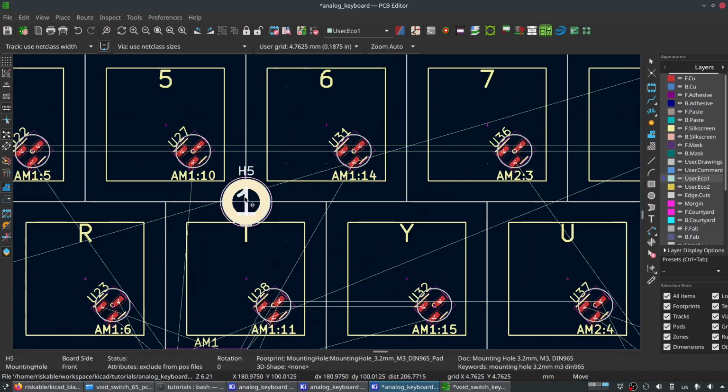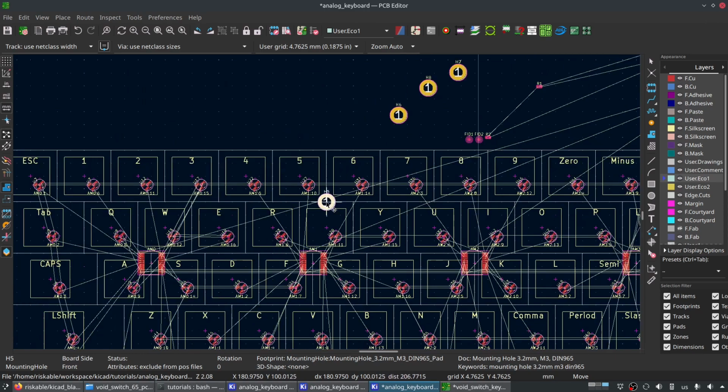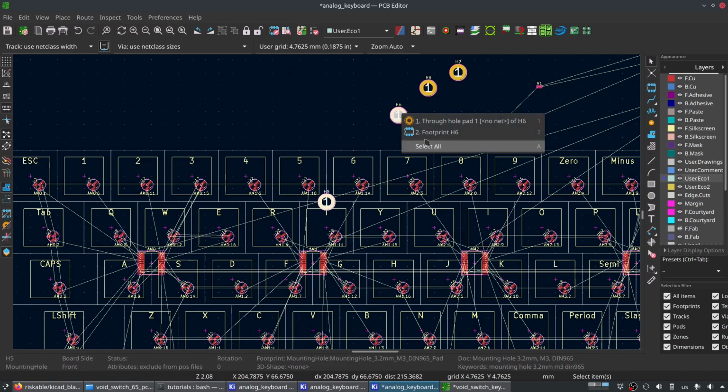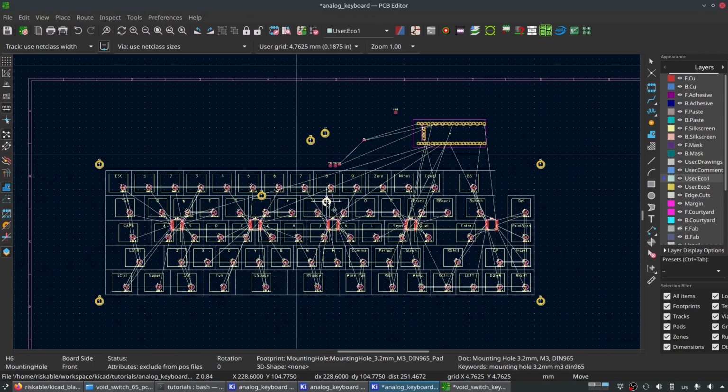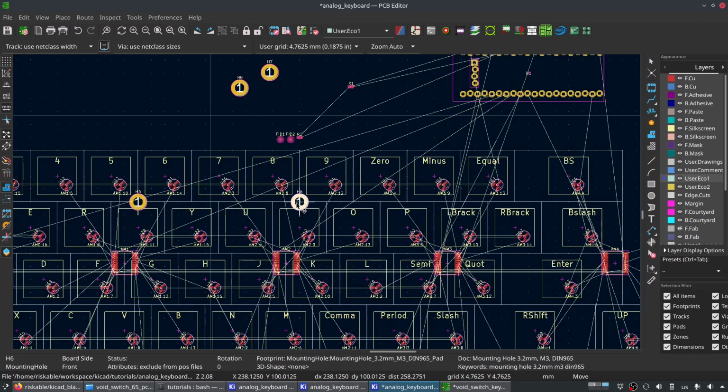At the top of a key is great, but at the bottom, see how it's so close to the Hall effect sensor? We don't want that. So if I have to put it here, I'll move it down a bit. But otherwise, I like to put it on the cross sections between the two here. That's actually not a bad spot right there. We'll do 6 next.